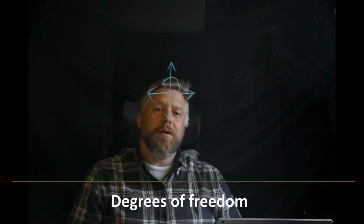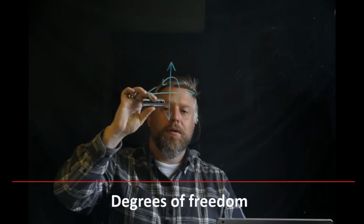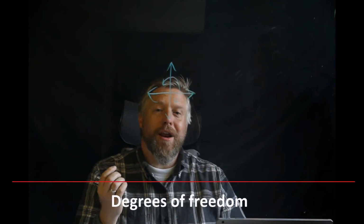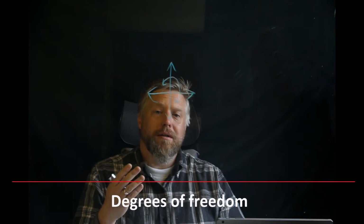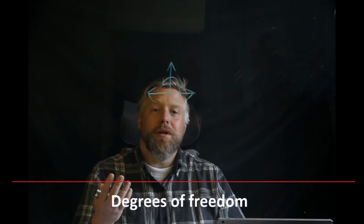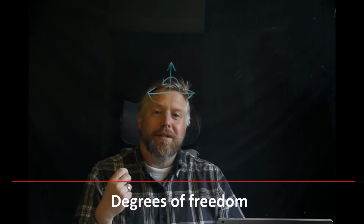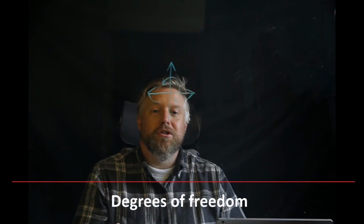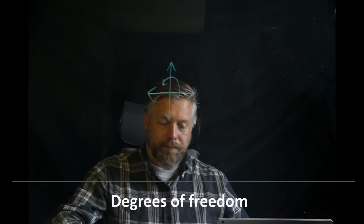So in 2D, we really have 3 degrees of freedom. You can go back and forth, up and down, or twist. And what we want to do when we're looking at supports is ask ourselves, how many degrees of freedom does this support restrict? In other words, how many degrees of freedom do we know it's not moving in? And then we're going to have to talk about static determinacy, whether our object is actually in a situation of equilibrium. But let's move on to a few supports.